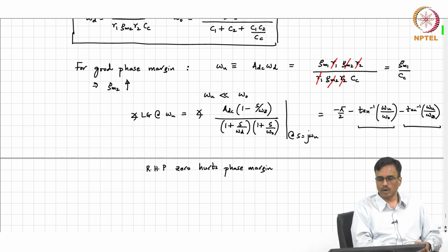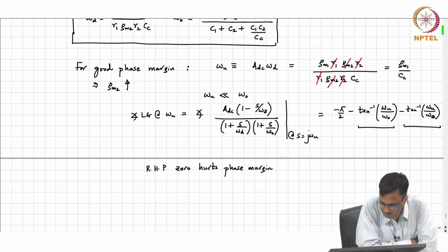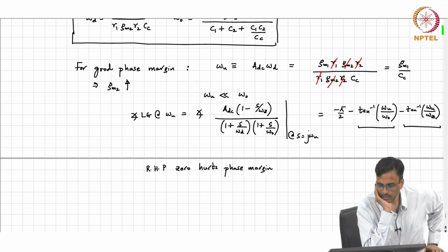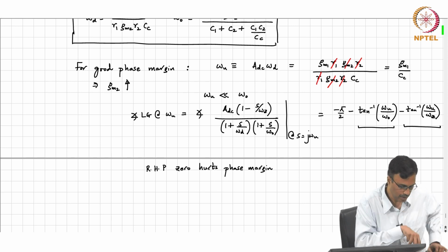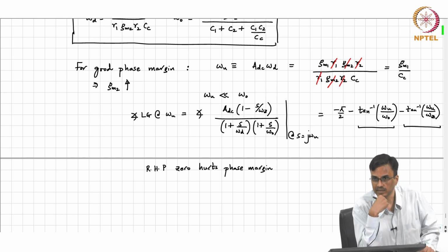All right. Now, a couple of things. As you know, there is a trade off between phase margin and the unity gain bandwidth. And by the way, the unity gain bandwidth of the op amp itself is GM1 over Cc, correct.